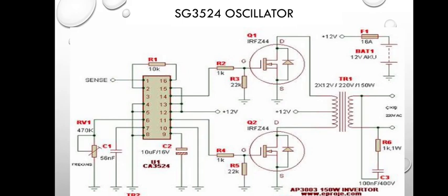So in every circuit you are designing, so long as a MOSFET is there and it determines the MOSFET switching off immediately the system is off, then it is advisable you connect this resistor. Instead of 22K, you can use just a 10K resistor. You can use 10K, it is widely used.